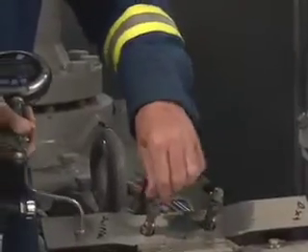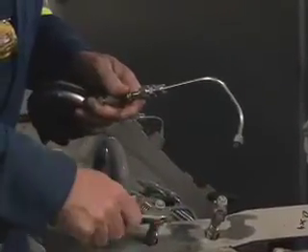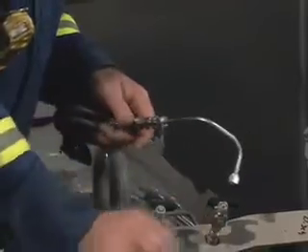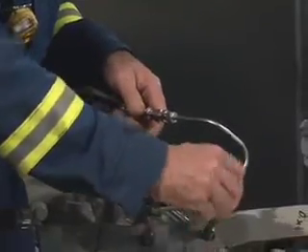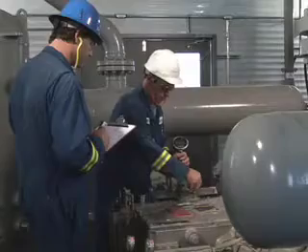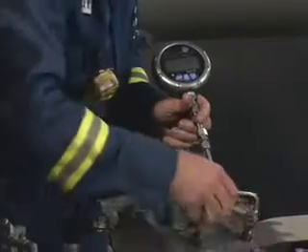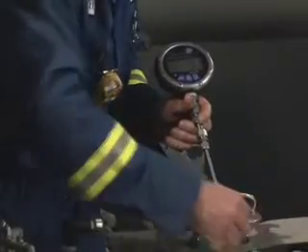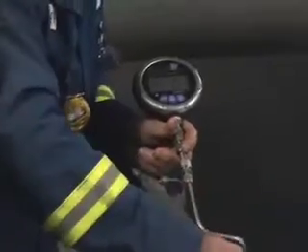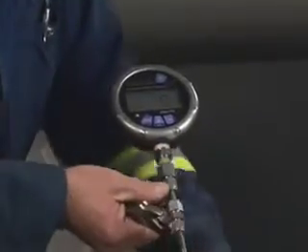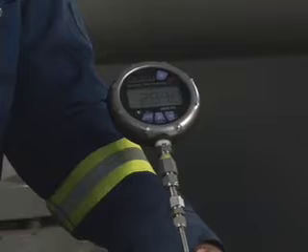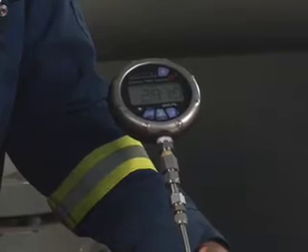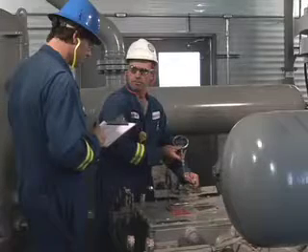These pressures should be measured using a digital deadweight gauge for best accuracy. In order to facilitate the collection of the pressure readings, many Detechtion clients have built a manifold onto their control panels with appropriate tubing, valves, and quick connectors to take all of the required pressure readings with a digital deadweight gauge. If this is not possible, then the pressures should simply be recorded using traditional panel gauges.